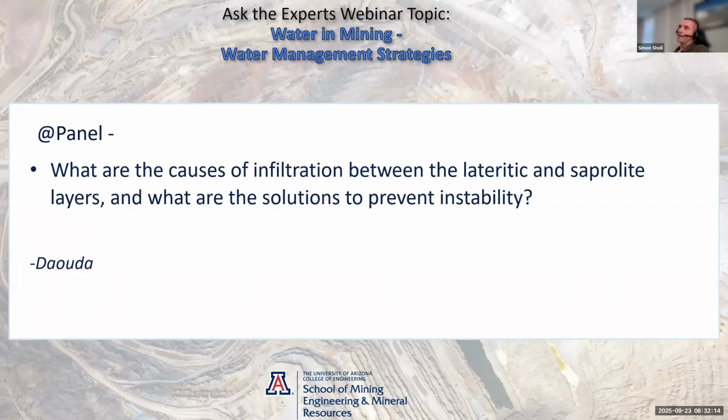So if you're monitoring that, you may feel that you're not depressurizing very much or dewatering very much, whereas actually in the saprock layer above it, you're having quite a significant impact. So you need to be sure that you really understand your environment and you're monitoring those changes and understand what those changes mean in relation to the different layers within your system.